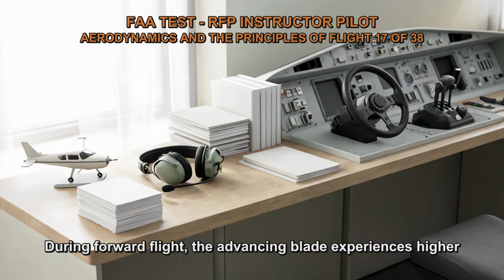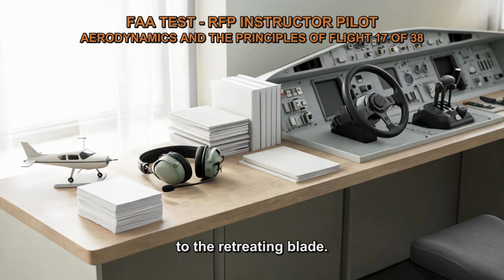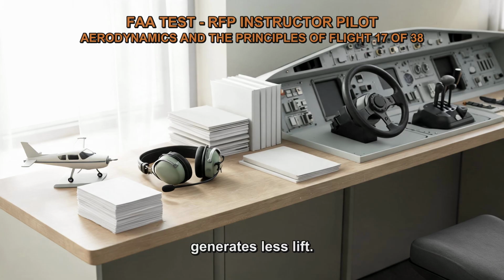During forward flight, the advancing blade experiences higher relative airflow speed and generates more lift compared to the retreating blade. This is due to the combined effect of the rotational speed of the rotor and the forward speed of the aircraft. The advancing blade, with its higher airspeed, has a higher angle of attack and generates more lift, while the retreating blade, with its lower airspeed, has a lower angle of attack and generates less lift.